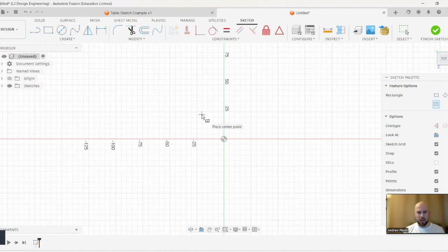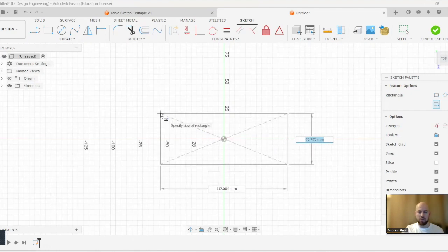If you pay close attention to what the cursor is trying to communicate to you, you start to realize how the sketch environment works. So what we're going to do is hover the cursor over. And as I said, that cursor is going to change. And at the minute, it's telling us it's being placed on the origin. Now that is exactly what we're looking for. So I'm simply going to left click. You don't need to click and drag, just click once and then start moving the mouse.